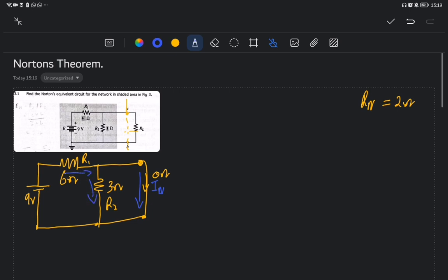But now remember the current wants the section of least resistance, right? So what you will do is understand that no current will flow in this resistor. All the current will flow this side. But for the sake of not changing the circuit, at this level of electrical Eng1, we will take a wire as 0 ohms, which will make this wire and this resistor in parallel, and then this resistor and the combination of the two in series.